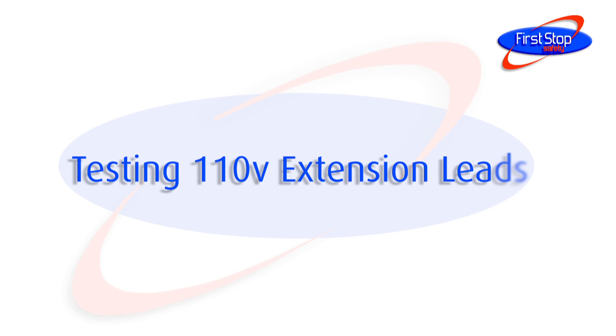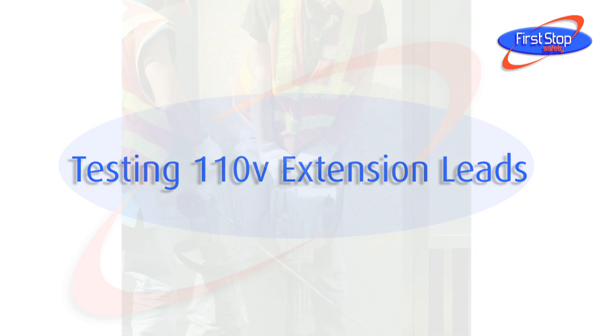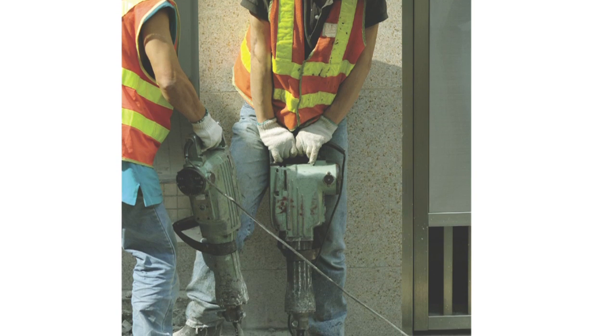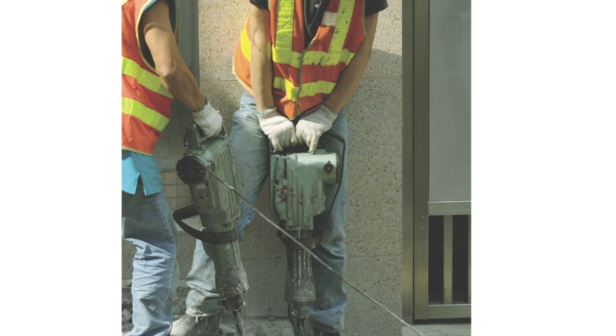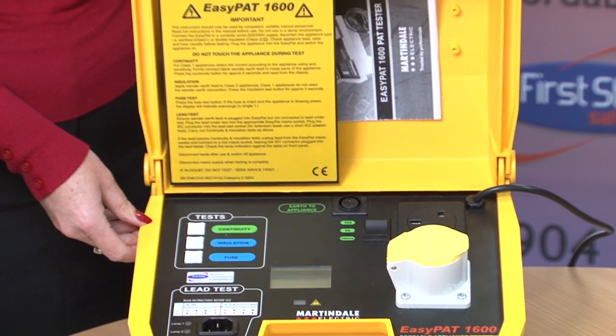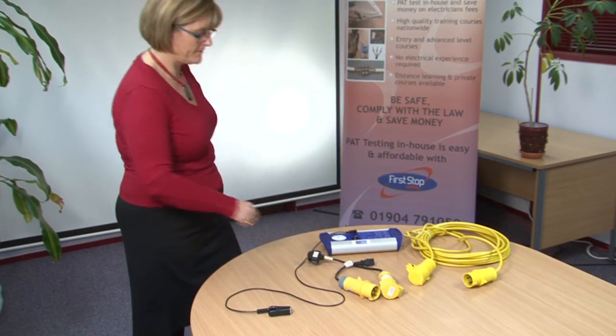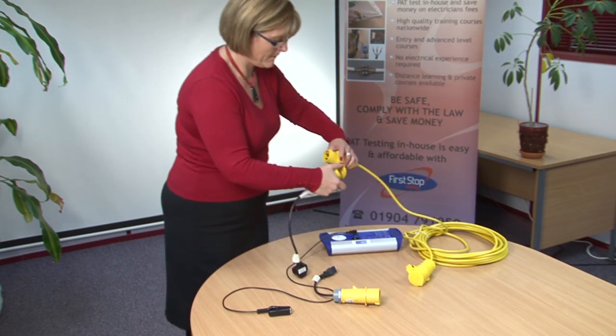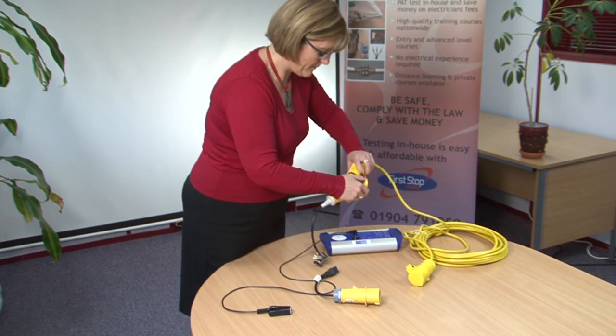Testing 110-volt extension leads. 110-volt extension leads are often used on construction sites. In order to test this, you'll need a PAT tester with a 110-volt socket. Alternatively, you can use an adapter like the one shown here with a normal PAT tester.